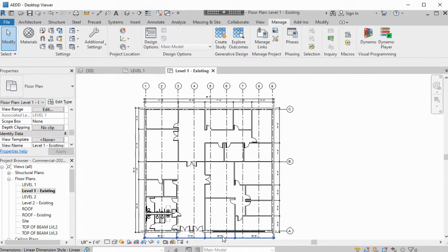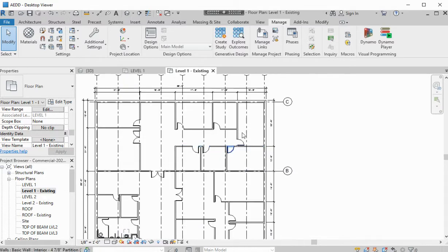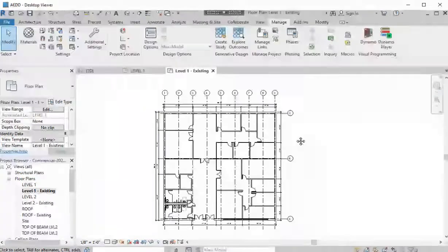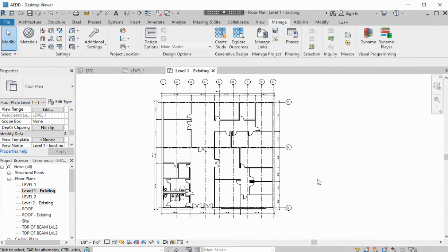So we're actually going to get rid of these two column grids here, because what I decided to do is remove the columns from inside the wall. But actually it's locating a beam. So there will be a beam that's supporting the structure. The beam will be resting on the CMU block wall, but the CMU block wall will say is supporting the beam. So we're going to add those elements to this.